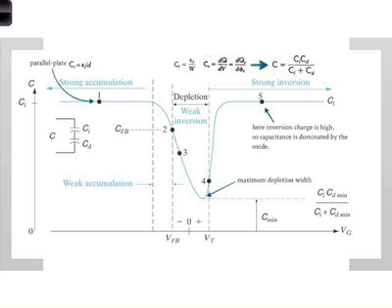There are two more things to keep in mind. Let me very quickly mention: the capacitance is a little bit different than what you're used to in a parallel plate. The reason being that the mechanism for the charge transport is very different than in a conventional parallel plate capacitor. In a parallel plate capacitor, when you apply a potential to metal and switch it, so you have an AC voltage going through, the charges are sloshing back and forth from the battery.